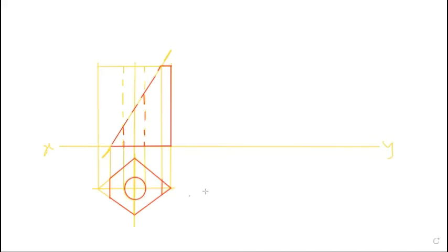Now we do the true sectional view. So for the true sectional view, first we go step by step. First we do the prism part. Then we do the whole cylinder. Okay. So for this, what we will do? Same way, here the angle 60 degree. So if we draw a 30 degree line, we get the 90 degree of this cutting plane. And here the cutting plane position bisects the axis. So the total height will be 56. So from the center to this point will be 28 millimeters.